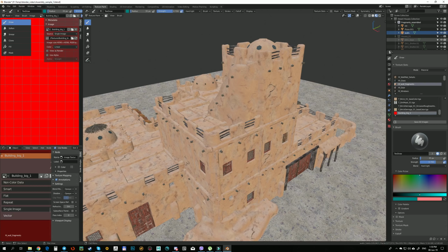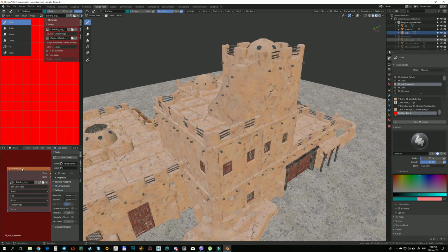It's very important that in your shader graph you select your blend mask where you are making your painting, because if it's not selected, when you hit Ctrl Z, it will always change here in the selected texture options to some other texture, and it will be very inconvenient.